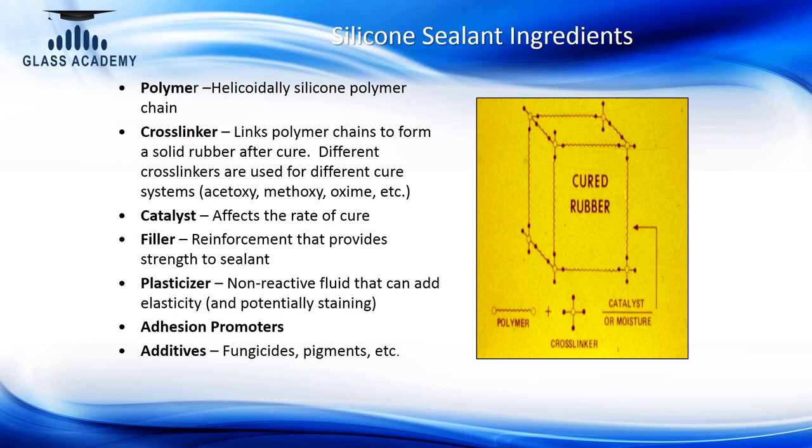The essential thing to understand on this slide is that the silicone sealant is made with a lot of materials added to it. One of the main things that impacts the property of this product is the polymer, the siloxane polymer we saw. That polymer has to be added to make the sealant. The amount of polymer added varies the properties, and it is an essential backbone which gives very good mechanical, physical and other important properties to the product.